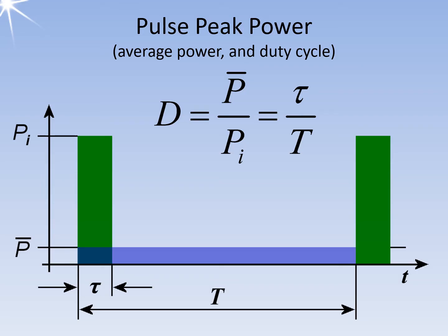Now, power is easier to measure than energy quantities, which is why the transmit power is used as the basis of calculations for radar. The power supply must provide only slightly more than the average power. The average power is usually stored in capacitors or delay lines. These components are discharged during the short transmission pulse length. A continuous wave radar will achieve the same range with the energy in the average power as the classical pulse radar with its energy during the pulse power.